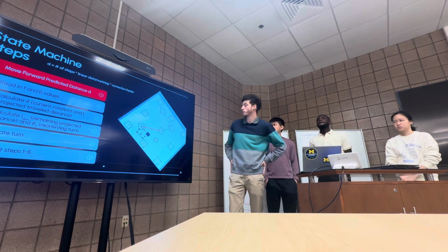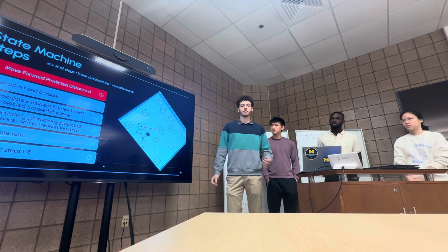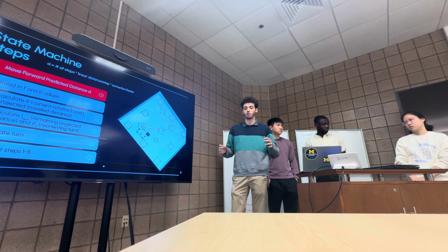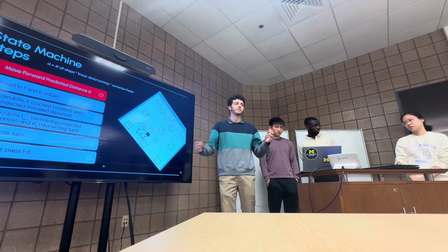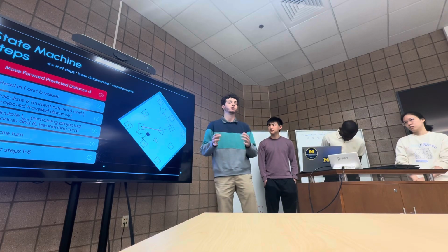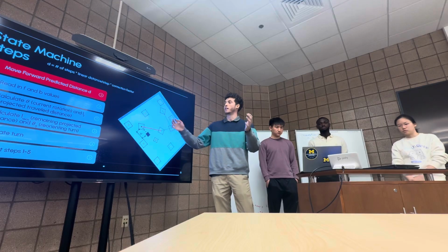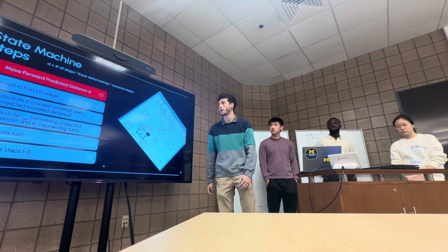So we'll start by moving forward a distance d. How do we figure out what we expect d to be? Well, we set up some experimental procedures. The idea being that we can tell our robot through code to move forward X number of steps, or move forward for an X amount of time, and then we're able to work backwards, take the physical data that we're able to collect, create a linear regression plot, and figure out exactly how much we're moving each time we tell it to move X amount.